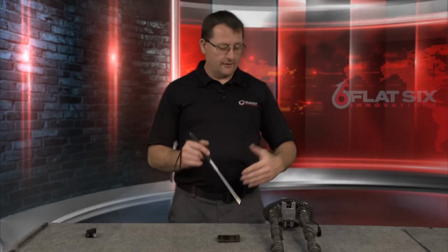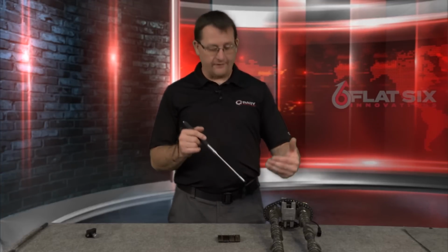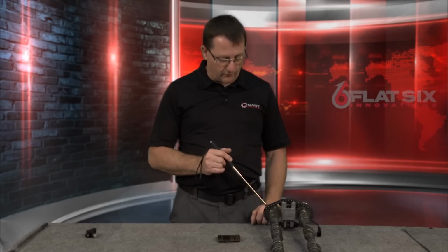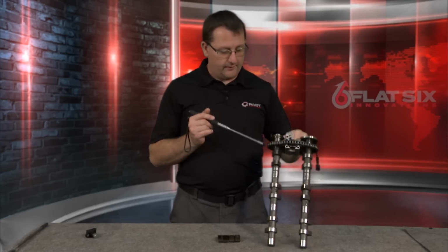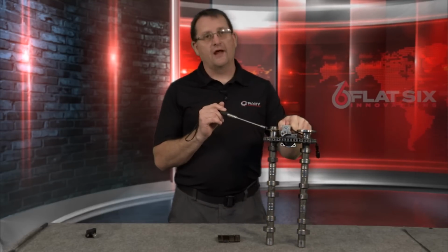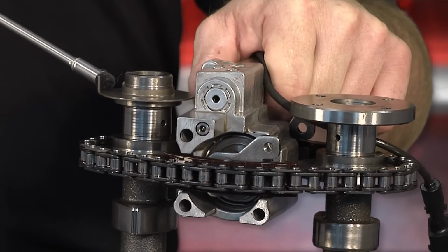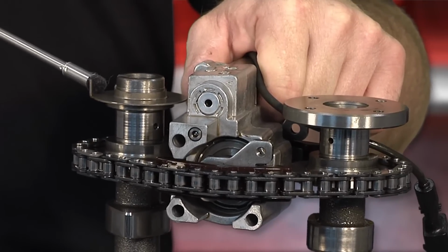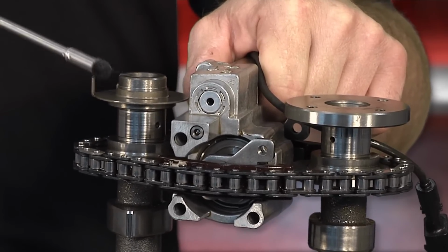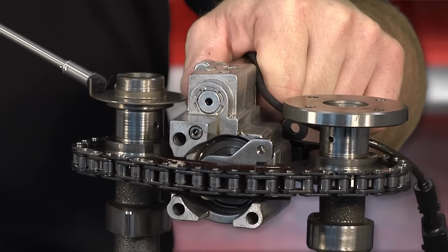You're going to have to take it apart, look at your chain guides, make sure the chain adjusters are in good condition, make sure that the reluctor wheel on the camshaft, which is another variable, isn't trying to come loose. We've seen these try to work loose before, especially on the 3-chain engines. They're actually on the other end of the camshaft, and we've seen those be off from the factory.